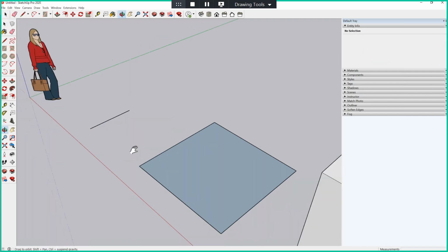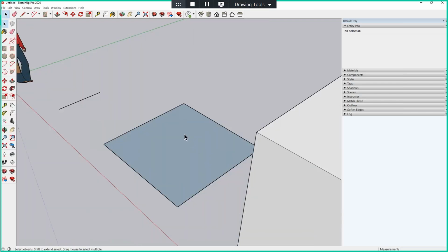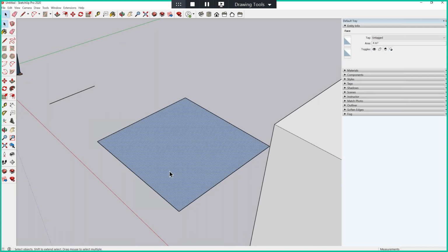For the next one here, you can see it's under my surface. So with the first click here, you can see that I'm able to extract my area from the surface itself. But do note, you only need to select the surface itself, not the surface and the bounding edges. If you do this selection here, you will not be able to find the surface area. So make sure that you're always selecting the right entity in order to extract the information that you want. You can also select the lines on the edges of the rectangle. By selecting these lines, you see that there is a length attached to it, but in this case, it is grayed out, and you're not able to change this length because it is connected to other entities.